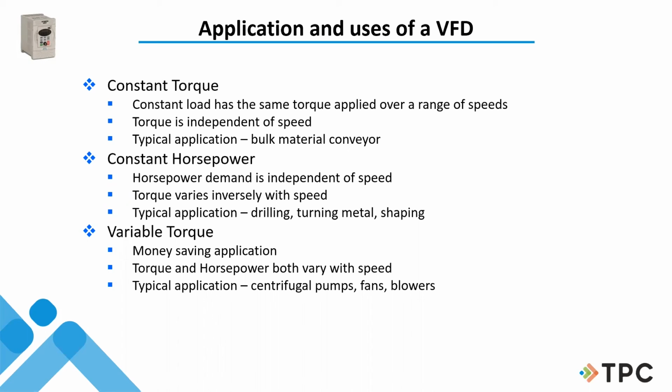I can make that all go away with a VFD, gradually ramping that pump or blower up, and take a lot of wear and tear off belts or couplings. So there's a lot of good things a drive can do for you. And in this case, this is where we can also save a lot of money. Payback in less than a year, probably, on installation and the drive.